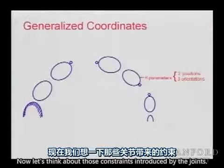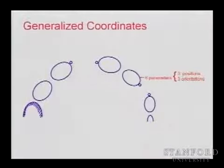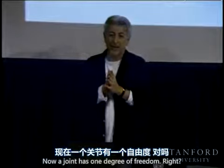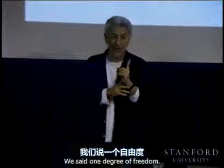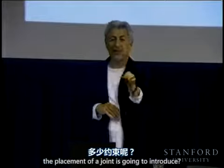Now let's think about those constraints introduced by the joints. If we put back the joints, we are going to introduce constraints. Now, a joint has 1 degree of freedom, right? We said 1 degree of freedom. So how many constraints is the placement of a joint going to introduce?